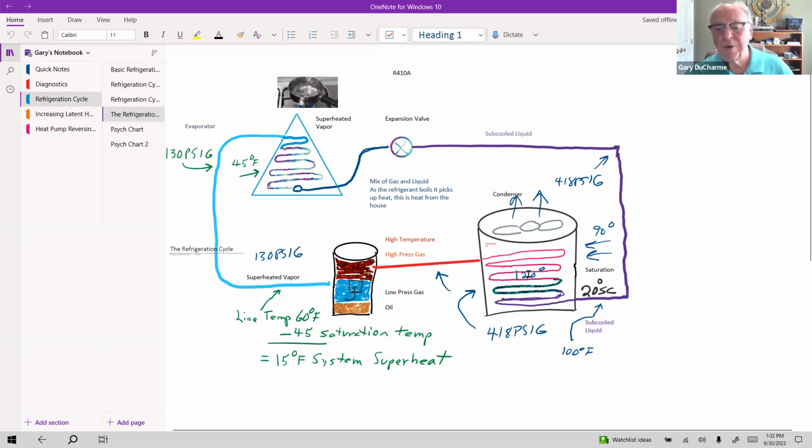Now, that heat that's in the refrigerant is the heat that we gathered in the room. We took it out of that 75 or 85-degree air. That heat is now in the condenser and we're rejecting it. We've added to that heat with the compressor, by compressing it to get it over the temperature of the outdoor air. That's the job of the compressor, to take in cold vapor and send out hot vapor. Then we cool it down with the outside air, which is cooler than the refrigerant, even at saturation.